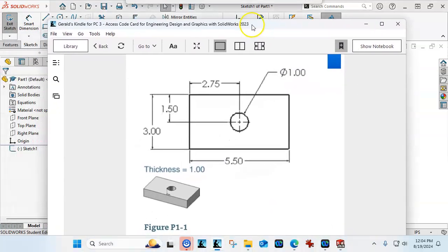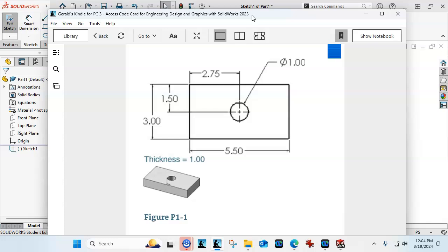So we're going to look at the drawing, and the recommendation is you watch this video and the next video, because this video is going to be with dimensions, and we want to take advantage of relations. So we're going to start talking about relations early and often, and the dimensions are in effect a relation. They do not exist outside of that structure. The parametric definition is that the dimension drives the geometry, the geometry does not drive the dimension, in most cases. There are always exceptions.